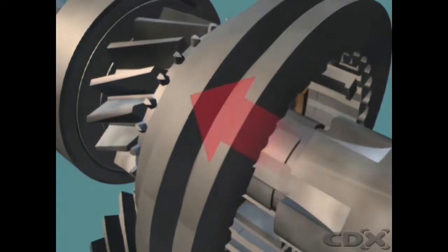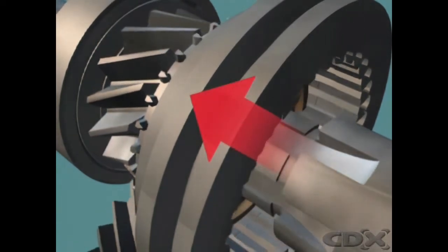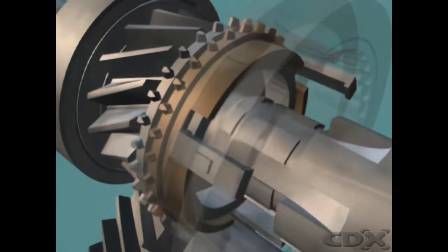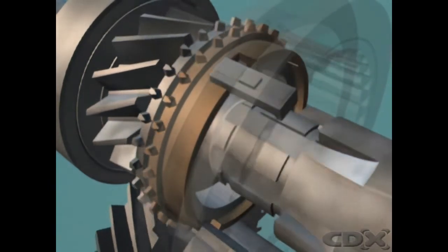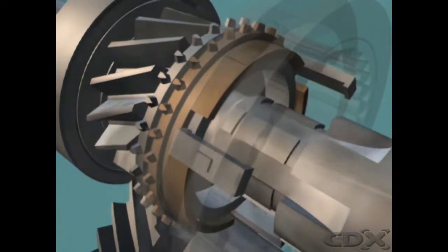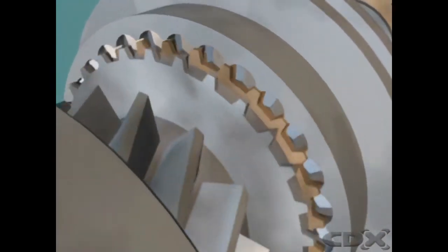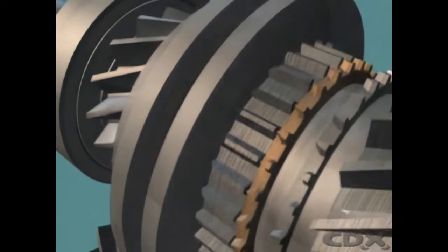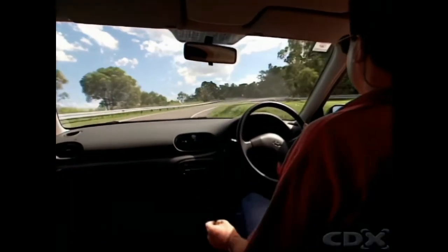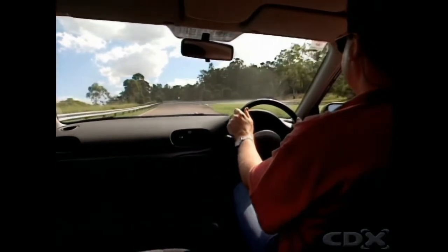The force exerted by the driver now presses the sleeve against the teeth of the balk ring and forces the conical face against the cone of the selected gear, until the friction created causes the two components to rotate at the same speed. The balk ring teeth can now come into alignment and the sleeve slides over them and into engagement. This is assisted by a chamfer on the teeth, which helps to guide the sleeve into position. Smooth and rapid gear changes are thus ensured.